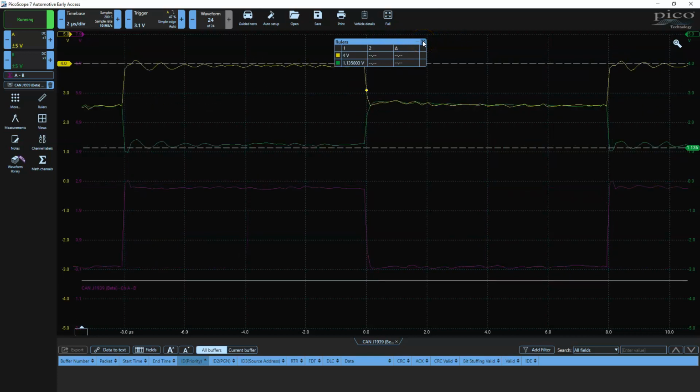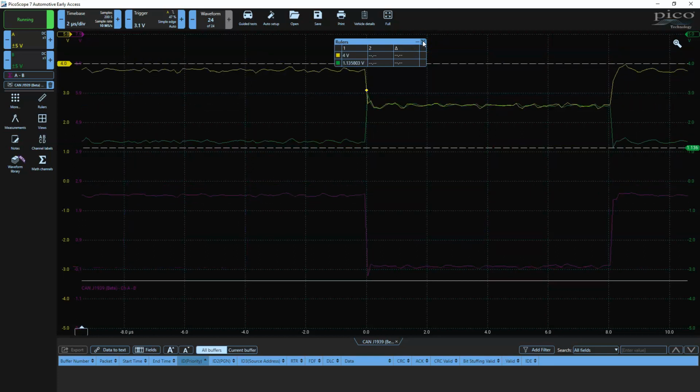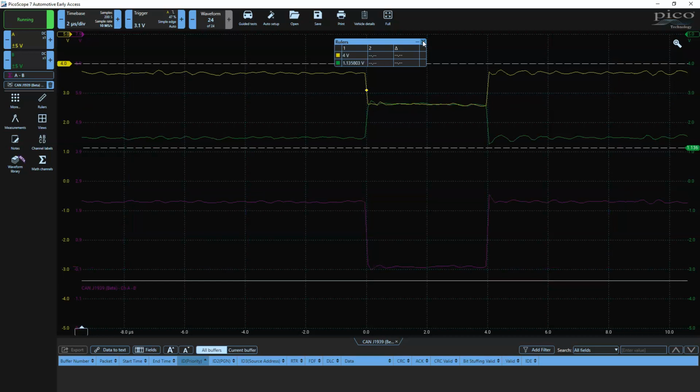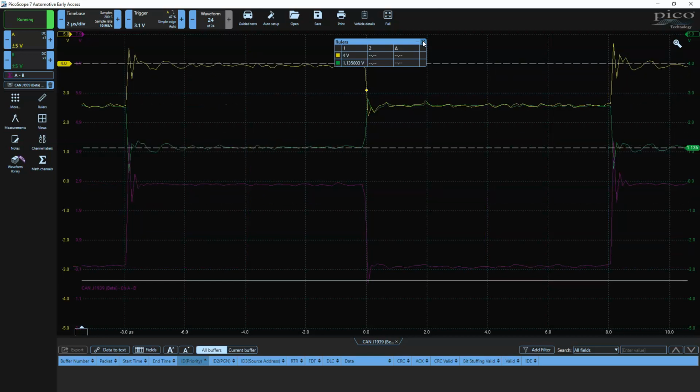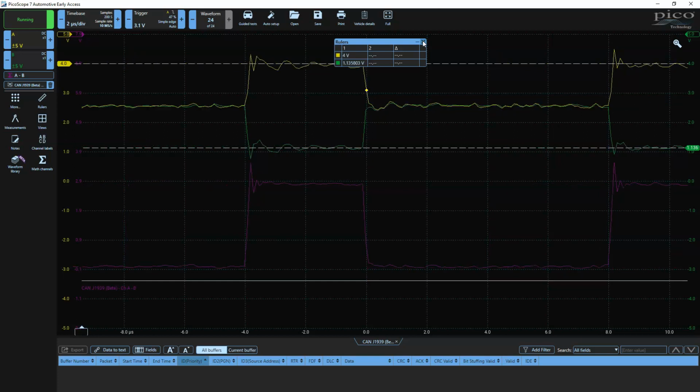I'll go ahead and plug it back in one more time. So we'll plug back in the terminator. It really doesn't change much. You can see the voltage decreased because we're now driving into 60 ohms instead of 120. 220 is in parallel. There, I took it back off again. There's a slight change in that ramp, and it's not much at all.